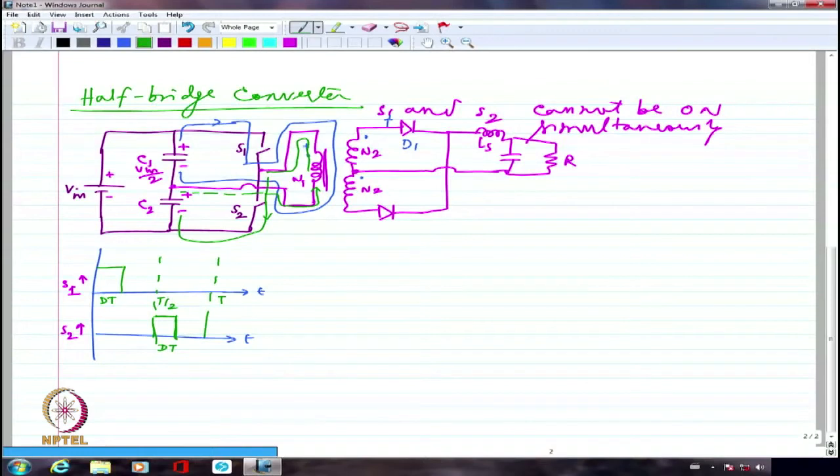So this is all square wave, clearly. Whatever we are getting is a square wave, because we are giving V in, which is a constant value. So for a DC-DC converter, all this will work. There is no problem. But when we are looking at inverter, we have to look at modulating this wave in such a way that we get a sinusoid. How do we get a sinusoid? That is a major chunk of the control of the inverter, which we'll be looking at eventually.